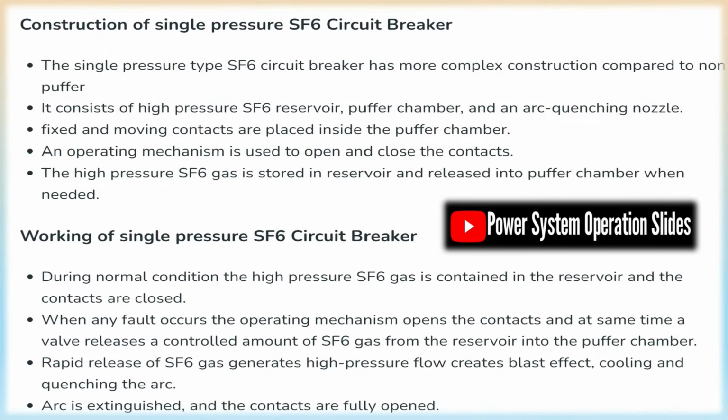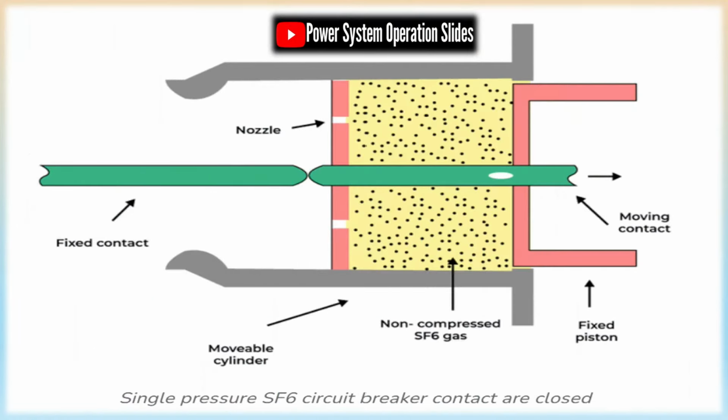There are also several different ways in which the electrical current and resulting arc in an SF6 circuit breaker can be interrupted. These types include double pressure, now obsolete; single pressure, also called puffer; self-blast, where arc energy supports pressure buildup in the arc chamber; rotating arc, which rotates electrodynamically in cool background gas; and double motion technology with two moving contacts.